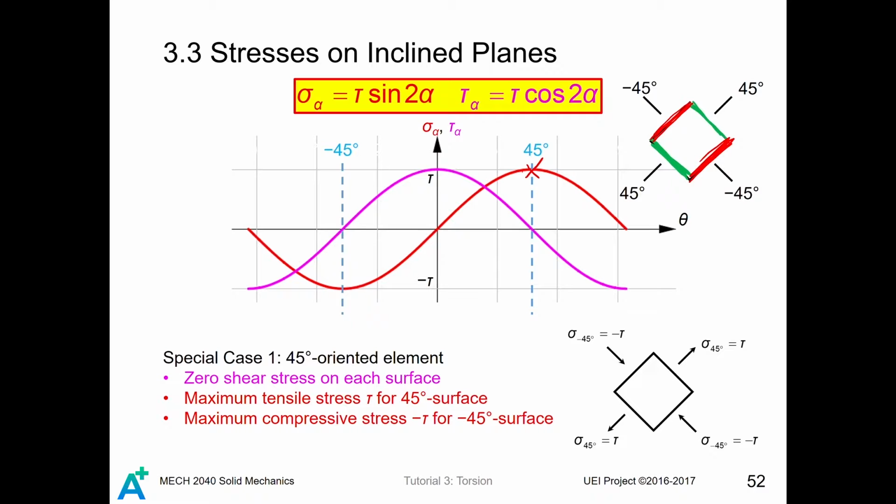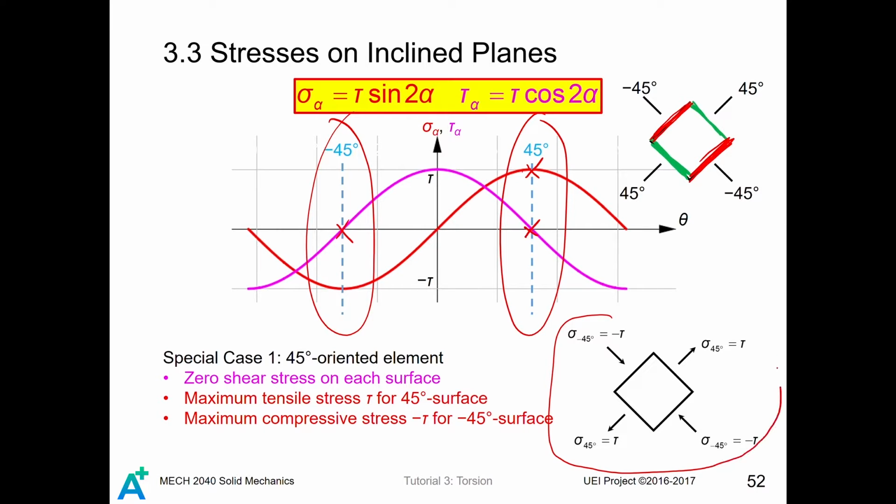Besides, we observe that for both of the two angles, consider the purple curve representing the shear stress. There is no shear stress on those two alpha values. That means for the entire stress element, there is no shear stress acting on it.